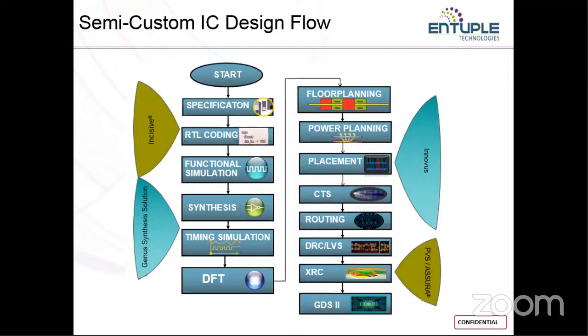It can be Verilog or VHDL or System Verilog or C program, System C, etc. Once you have completed the RTL design, you'll be working on the functional simulation. You cannot directly simulate your design, so first you need to go through the compilation.